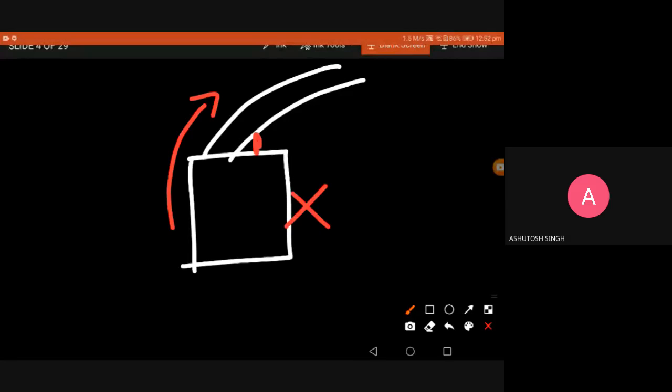Now I'm thinking about how I'm going to design the circuit. I'll come up with a circuit like this. I'll draw my photo transistor. So whenever radiation falls on my base, it gets on. So what is the idea? When my photo transistor is getting on, my motor on that corresponding side should get off. Now I think you might have remembered the NOT gate principle.